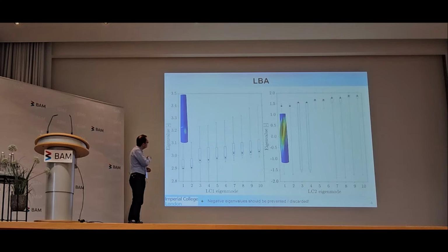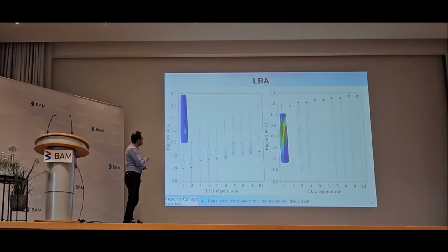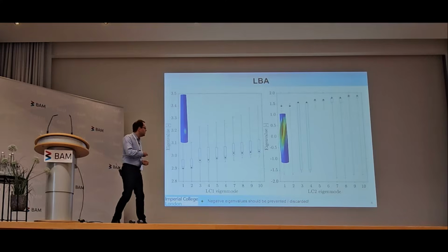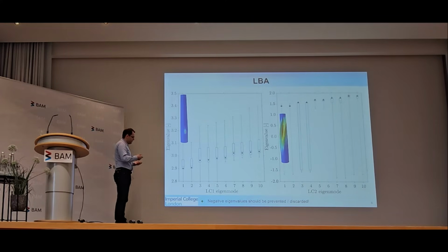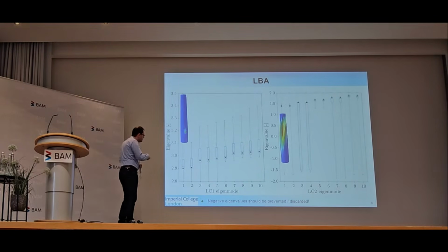displacements. And unfortunately, this axial compression buckle is quite a small buckle, which means that you have to have quite a fine mesh locally where the buckle happens in order to capture it correctly. So if you have a coarse mesh, you will get a very coarse representation of this, and inevitably a much stiffer one. And there is a consequence to overestimating the LBA mode, and the LBA resistance, as a consequence of a stiffer mesh.